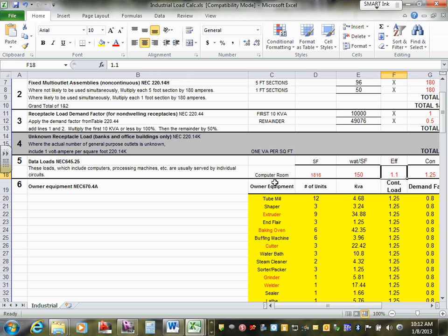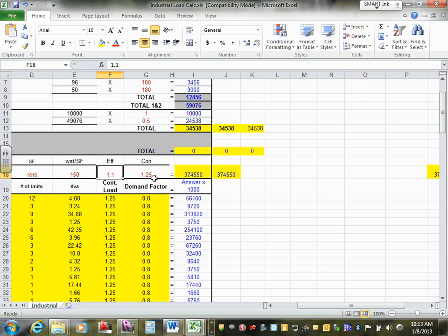Multiplied by efficiency 1.1. Because the system has losses in it, and because it's also watt versus amp, I up it 10%. That's what I'm doing. I just up it 10% to accommodate for efficiency and for the most part power factor. Everybody understand? Okay? And then you multiply it by 125%. Why 125%? Continuous load. So I'm really upping it a lot.